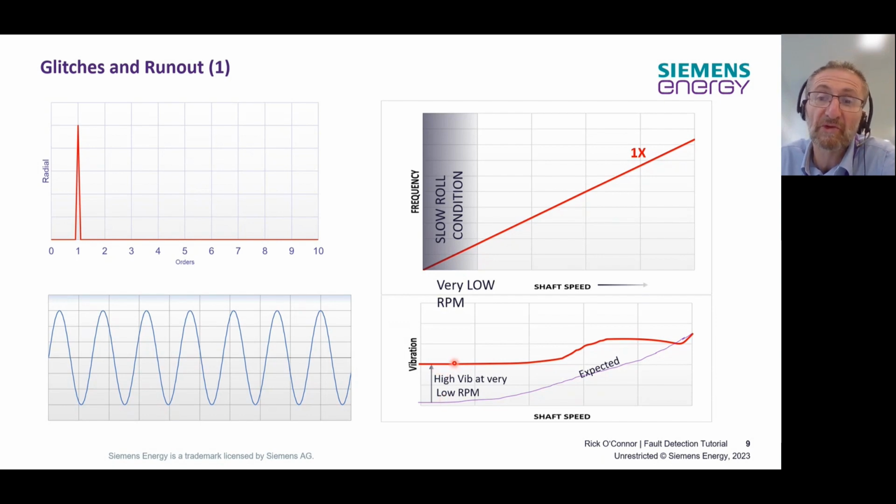Well, typically it's more likely to be due to something like electrical runout and variation in shaft conductivity, maybe local magnetic forces, welding operations. Mechanical runout may look like this as well, as would out of roundness and surface imperfections, to name a few. There are many others.